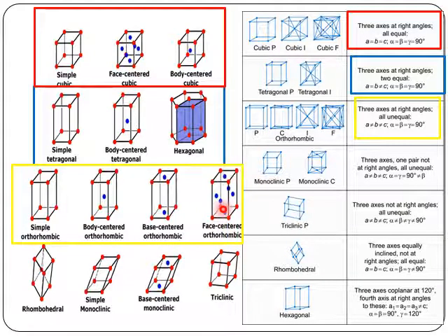Okay. So face centered means in each face, if you take a cube, there are 6 faces. So on each of the 6 faces, there is one atom which is shared by 2 unit cells. But in a base centered, only the top and the bottom face have atoms, 2 atoms. Okay, that is base centered. So body centered means only one atom at the center of a simple cube. Okay, so here A not equal to B not equal to C, and all the angles are equal to 90 degrees.